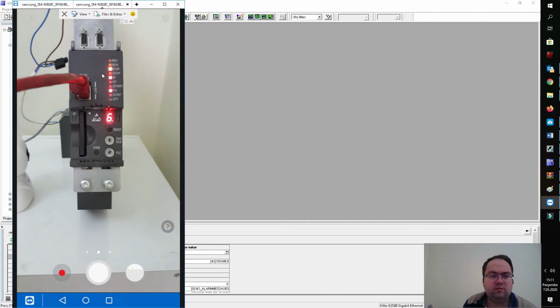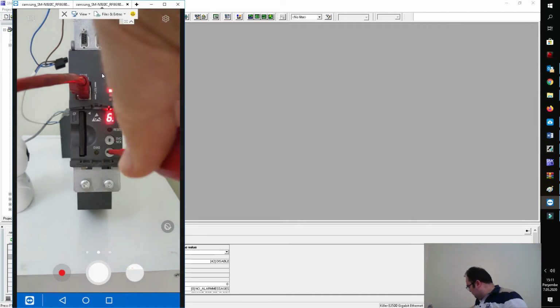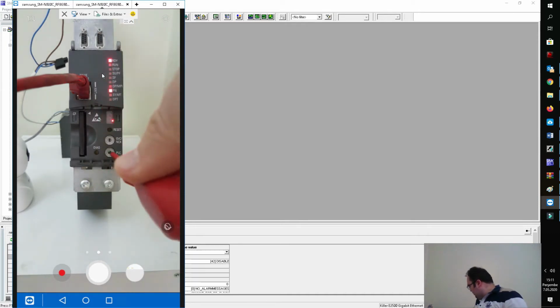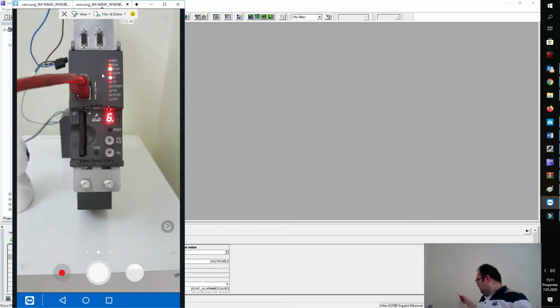For the memory reset, you have to go to switch mode 3. And you see the LED blinks. After you go back and try again, you see it's in stop mode. By the way, if you rotate the switch, you see the current state of your switch, and now the system is executing the memory reset function, and after that the system will be restarted.